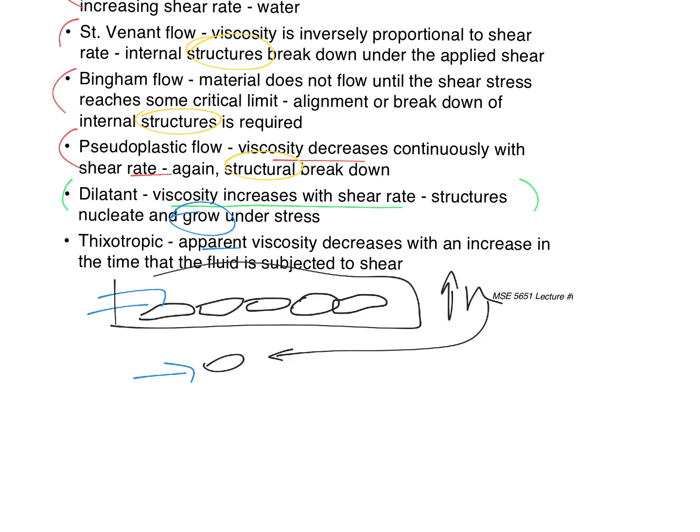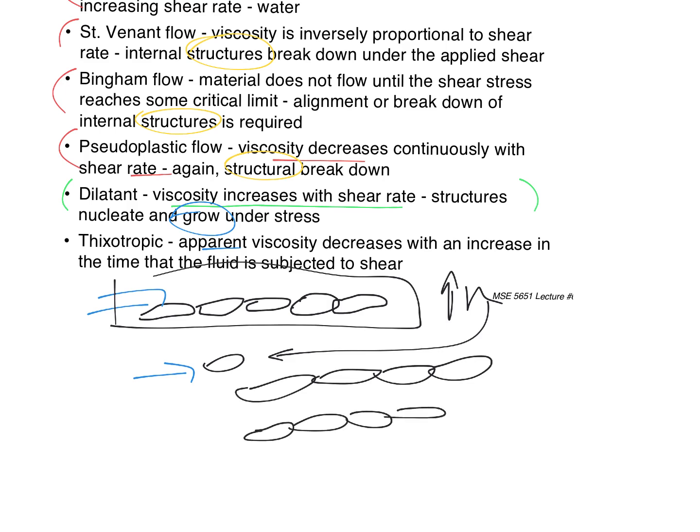We can also have different structures that consist of strings of particles connected by other particles. All right, so sort of a cellular, almost biological type structure. And so this can get pretty complex. And so this gives you an idea of why when we shear this, the viscosity can go up. If these structures form, if you start tearing these things apart, the viscosity can go down. All right. And so because we have these ceramic particles in there, surrounded by polymer, these ceramic particles can make these different types of structures inside of this melt. Any questions about that? Hopefully that makes some sense.